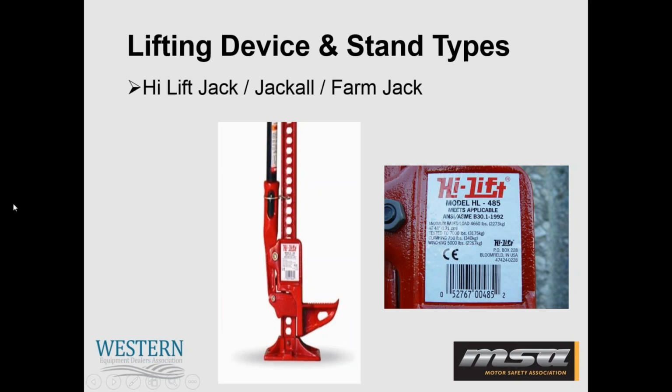So if you are purchasing or utilizing these types of jacks, they need to be in fact approved by a standards association. You also need to know the weight of what you're lifting and lift it straight so that you don't exceed this jack's lifting capacities. You also want to be aware of the base plate.